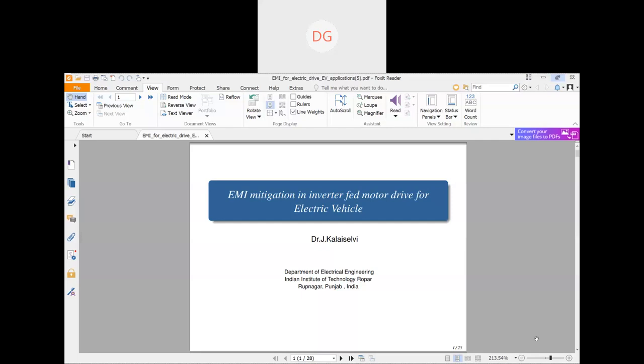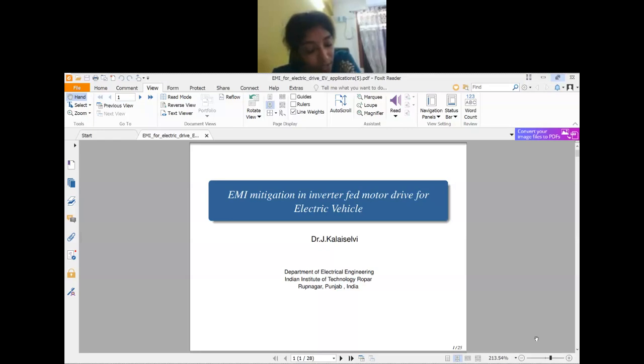The first thing on the control side is that people filter out. Once the measurement is done, because the information we need is at very low frequency, people first filter out all of the noise. In any control, the first processing will be filtering from the control perspective. From another perspective, when you make any system, the first thing we try to do is measure whether the noise is within a reasonable limit at all the points of interest, say at the output or at the input. You measure first when you install it itself.